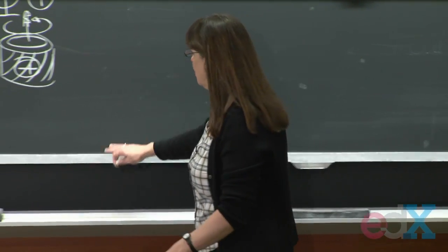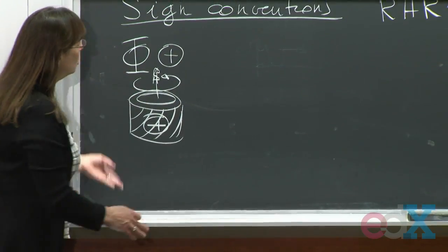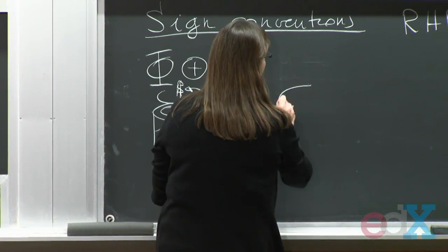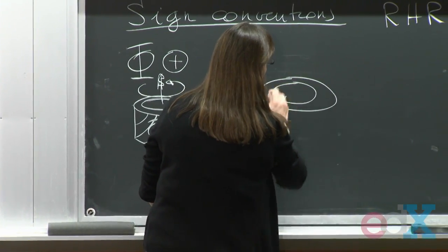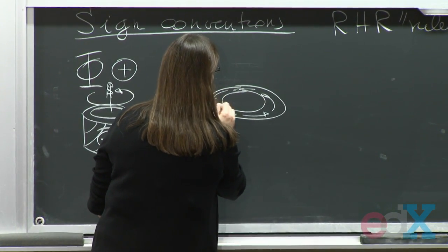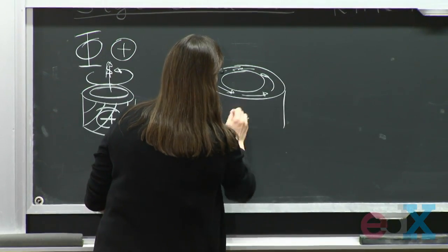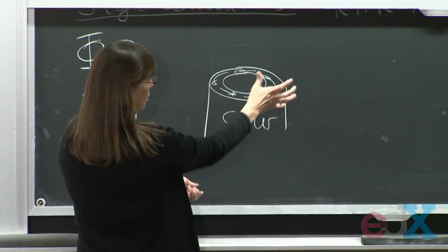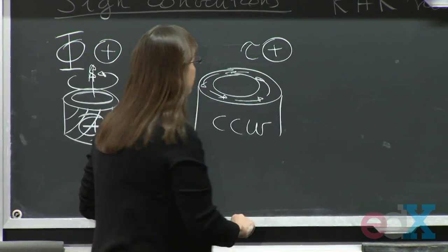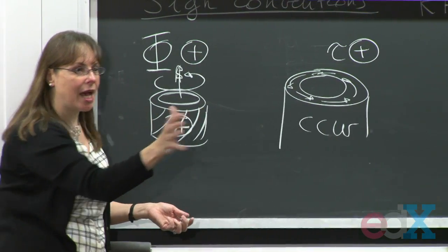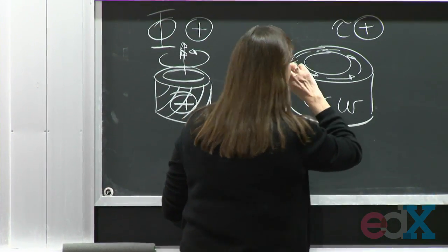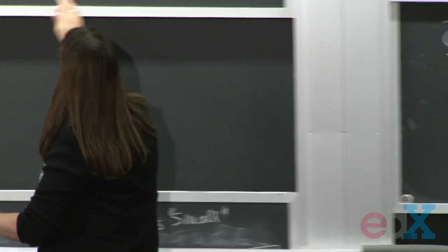It's really a disaster. Okay, so positive angle of twist. The stresses, same thing. So if this is my stress, if it goes around that way, counterclockwise, so my counterclockwise stress, like that, this tau is positive. Okay, same thing. If the tau goes around, look at the way the tau goes, it tells you which way is positive. The same way as when you do uniaxial loading.